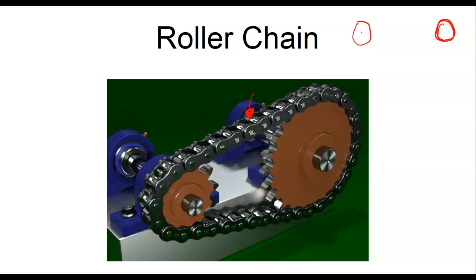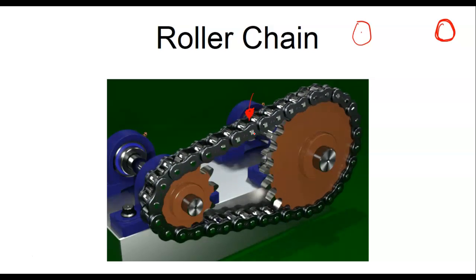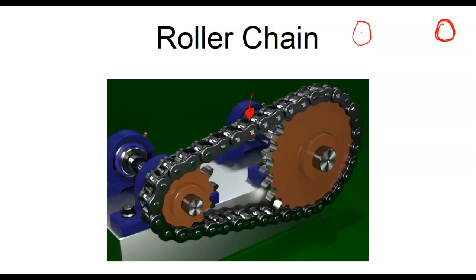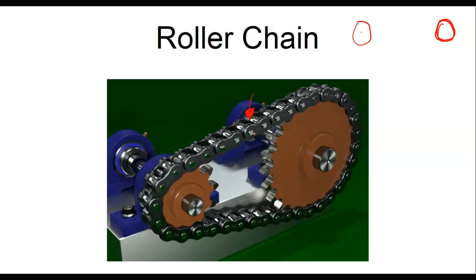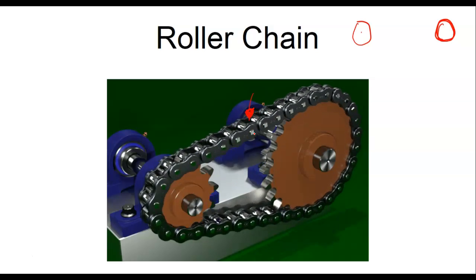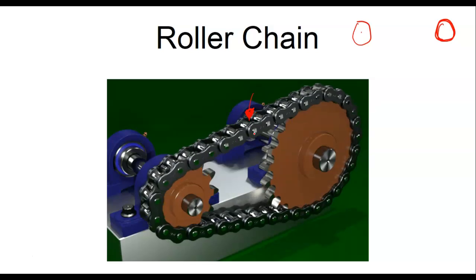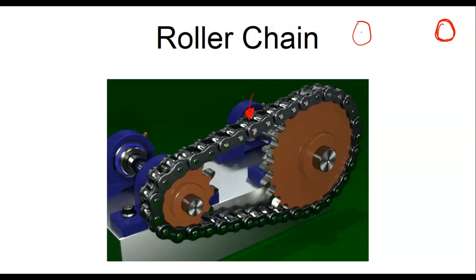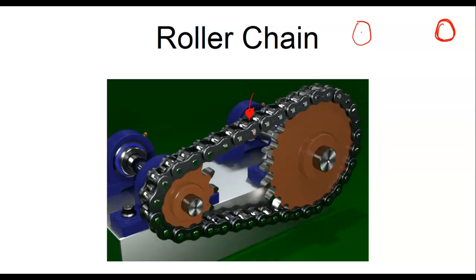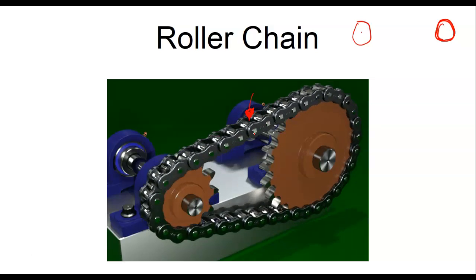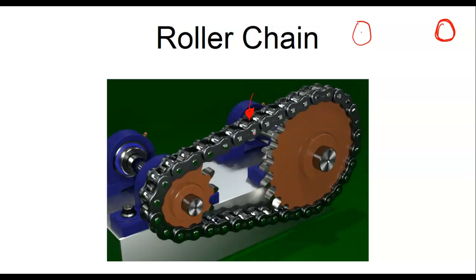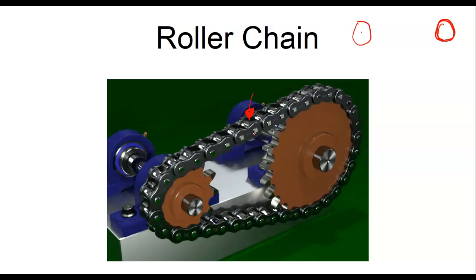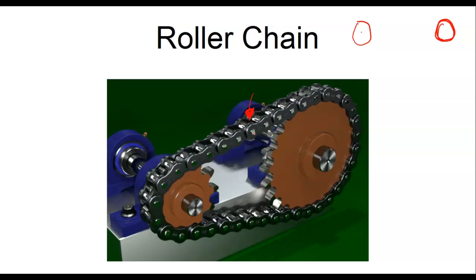So on a chain drive on a motorcycle, you usually had a lubricator back there. Basically, it was just a bottle that had oil in it, and it had a little whip on it that would ride on the chain and lubricate the chain. Anybody that's ridden a bicycle and put it up for a little while and come back, the chain's going to be rusted, right? And then you've got to get the kinks out and work it out. Sometimes you have to replace the chain. So you have to keep these things lubricated, but in and out is exactly the same.